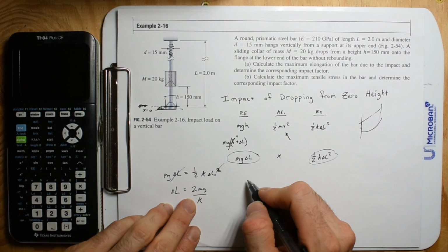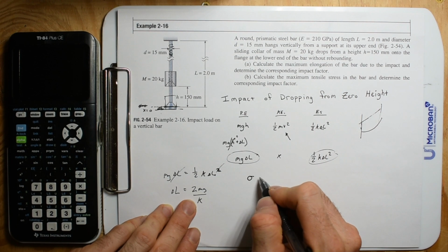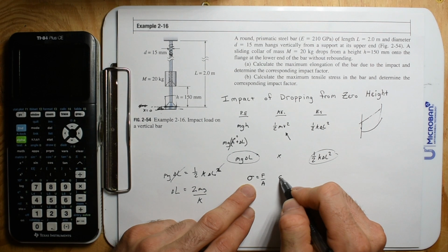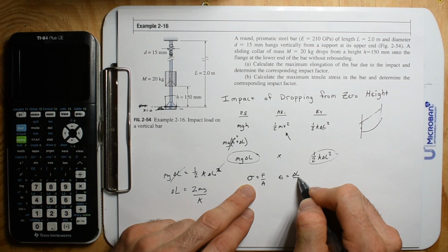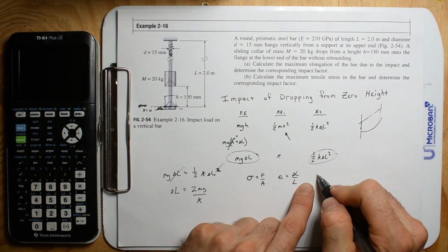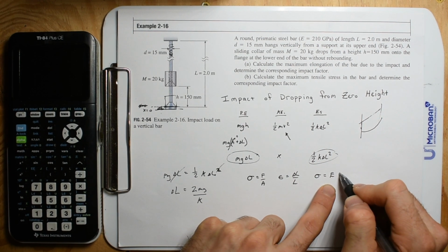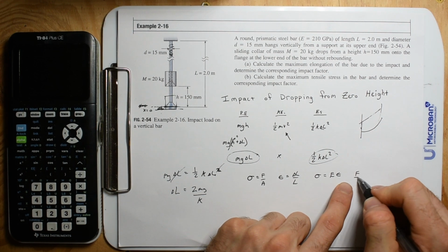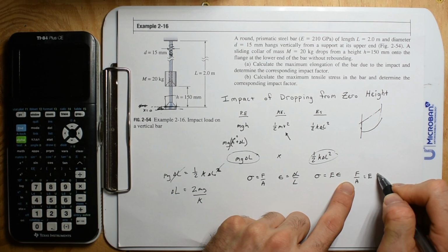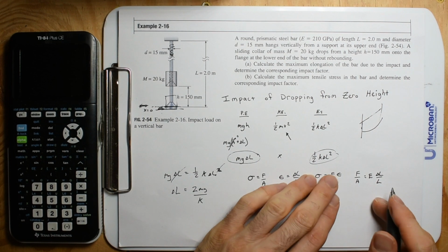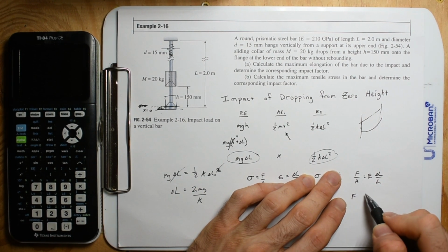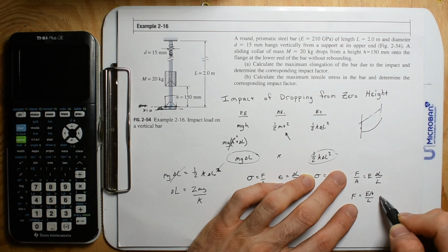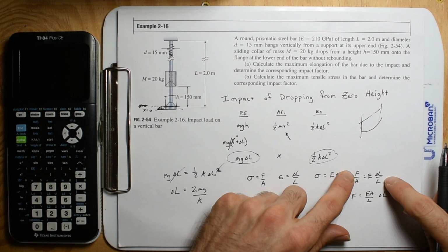Alright, but now here is where you need to go back to your material mechanics equations. Stress is force over area. Strain or stretch is change in length divided by length. The equation that relates these is stress equals modulus of elasticity times strain. So we can put those together: force over area equals modulus of elasticity times change in length divided by length. This is the first one I would do. I would get force all by itself. So A goes upstairs, we have EA, divide by L, and then put change in length off to the side. That's all we did, rearranged.